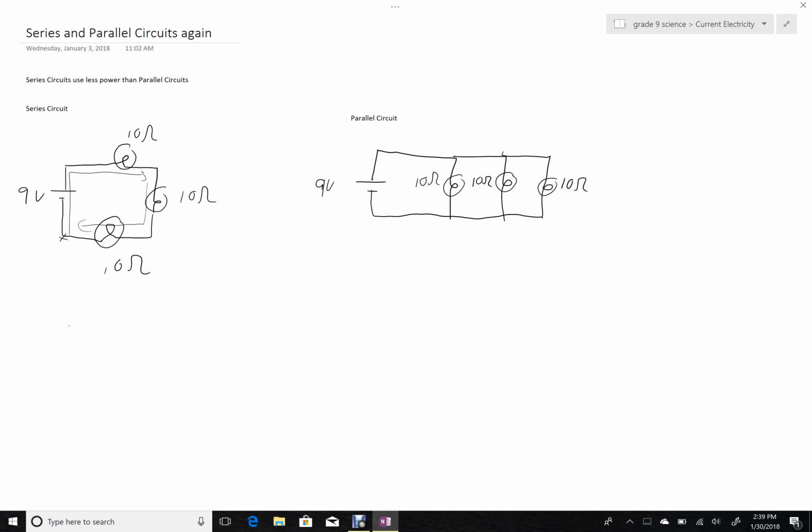Going around this voltage loop, I'm going to go up a 9-volt battery, and then down V1, V2, and V3, the voltage of the 3 light bulbs, respectively. Now, I don't have any common variable here, so I'm going to recognize that the current everywhere in the circuit is constant. And then it will be useful to replace all of those voltage expressions with equivalent expressions involving current, since it's the same current at all places in the circuit.